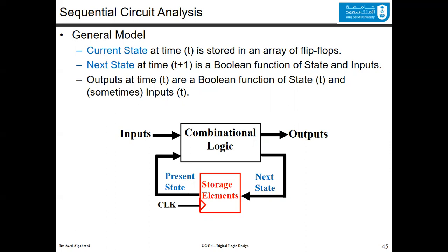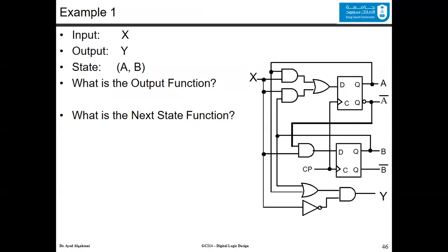As an analysis of the sequential circuit, when we try to analyze, you already have the circuit. It's already been done. You know its block diagram. And then from the block diagram, you try to analyze the sequential circuit and understand what's going on through that circuit. To give you an example, this is a block diagram of a sequential circuit. You know that this is a sequential circuit because there are D flip-flops, as you can see. Also, there are a few feedbacks. There is a feedback here, a feedback here. And because of this, you know for a fact that this is a sequential circuit.